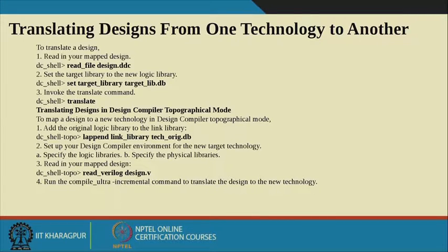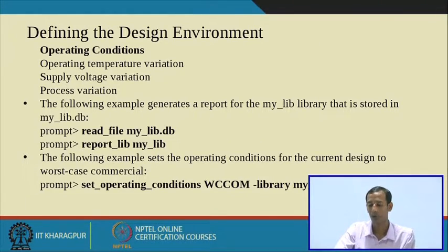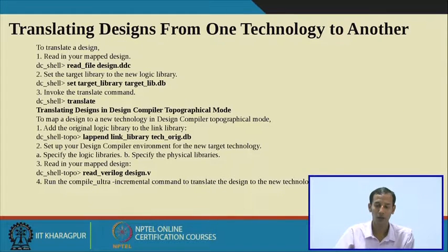After that, in the topographical mode, how can you do that? So append the link library with the original logic library, then read your Verilog file, and then run compile_ultra in the incremental compile mode. So this you can do.